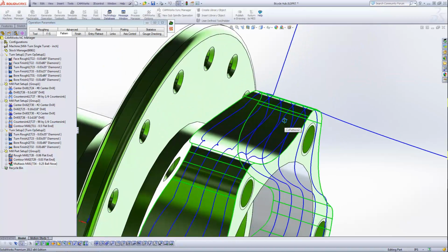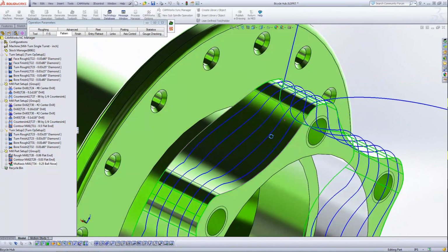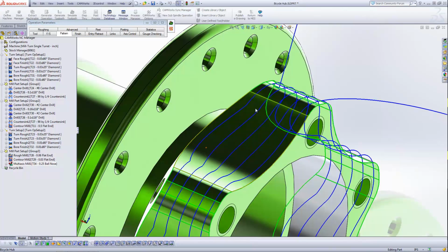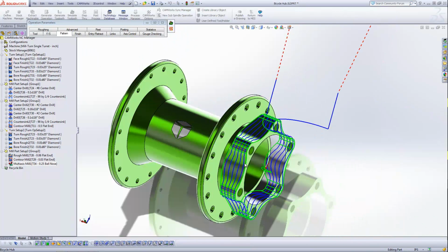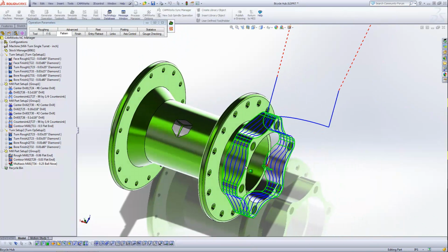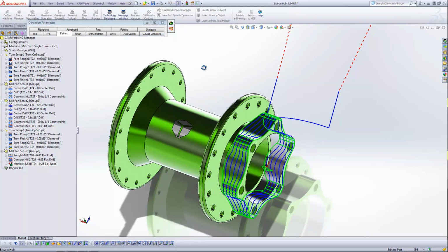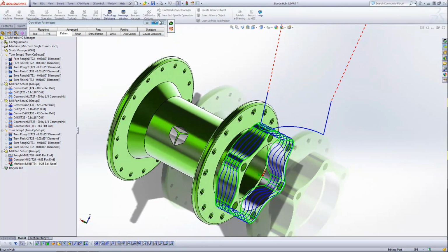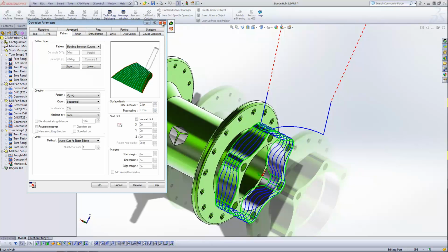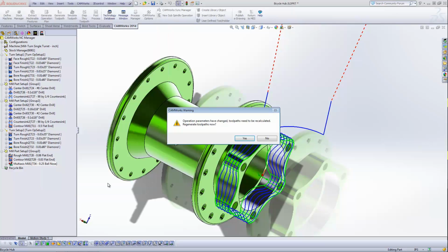So there we go. It's fairly simple to create that 4-axis cut. It's just going to interpolate between each side. Again, I can go into a lot of details on that, but in the interest of time, I just wanted to show you a pretty simple way to do this. And I would only need to do this if I'm cutting on a 2-axis machine, which I am.